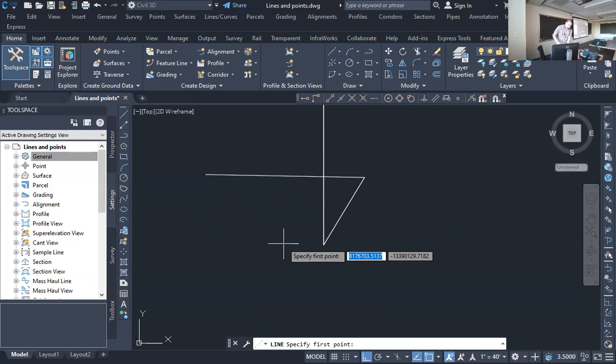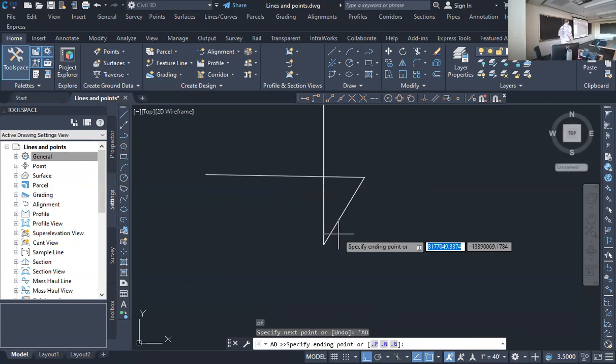So you type the word end, and you see how it gives me that little greenish colored box? Now you're selecting the end of that line. The next thing it's asking you for is that reference. So now you're saying, my backside is where? My backside is this last line.